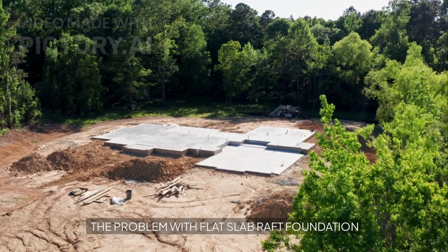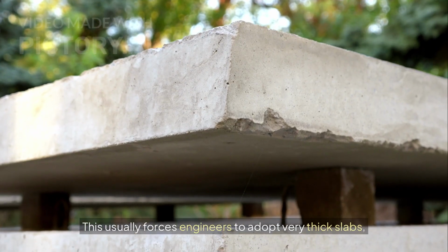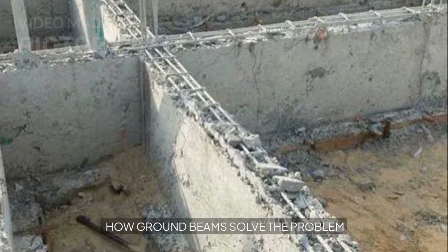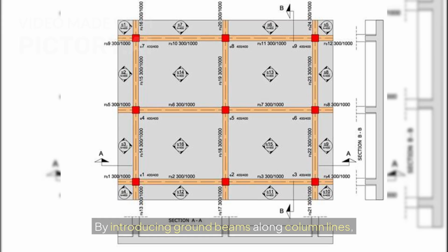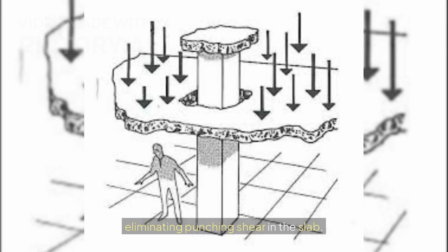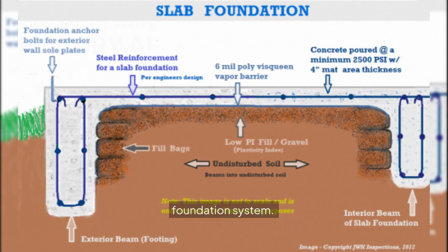The problem with flat slab raft foundation: in flat slab raft design, punching shear is often the governing design criterion. This usually forces engineers to adopt very thick slabs, which directly increases construction cost. How do ground beams solve the problem? By introducing ground beams along column lines, the column load is transferred through the beams, eliminating punching shear in the slab. This allows the designer to use thinner raft slabs, larger, well-reinforced ground beams, and a more economical foundation system.